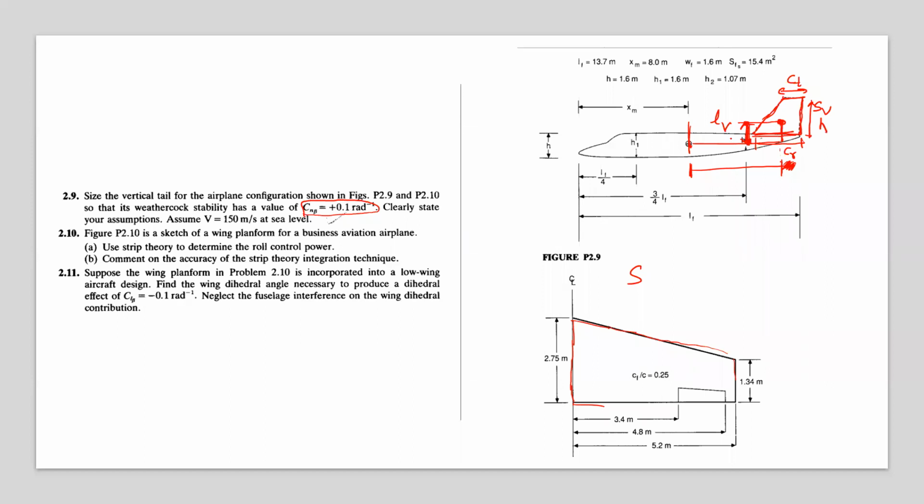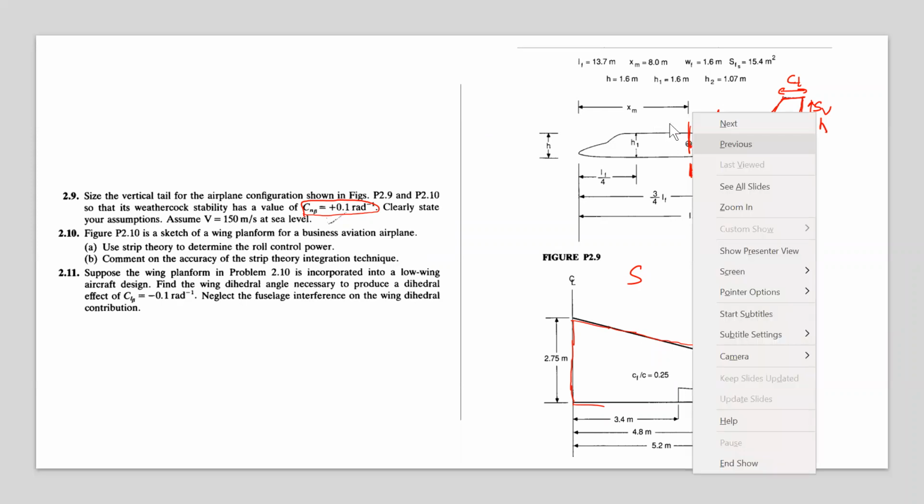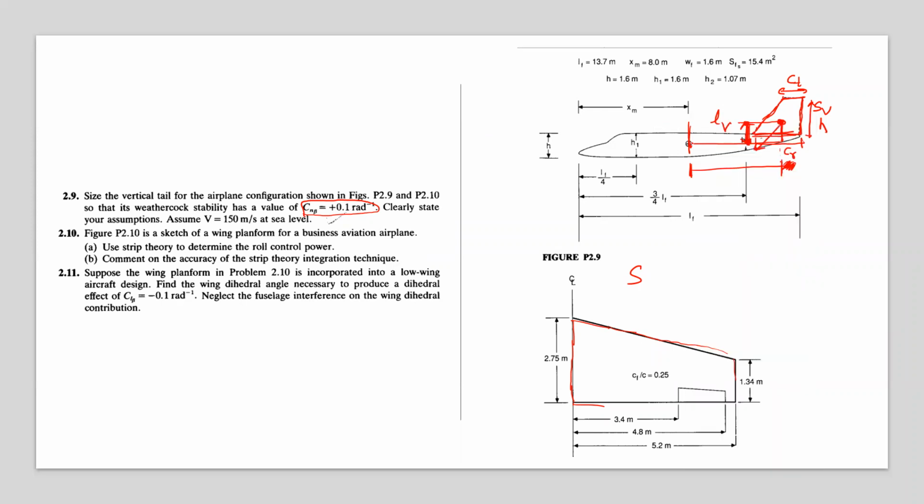Yaw moment. Anyone else? The vertical tail will give the yaw moment. That is absolutely correct, but that is with respect to the length LV. When you multiply that side force that it is experiencing with LV, it will give the yaw moment. But I'm asking, when you look at it from the side view, not from the top view. If you look at it from the top view, then definitely LV multiplied by that side force gives the yaw. Do you understand the difference in the two questions?